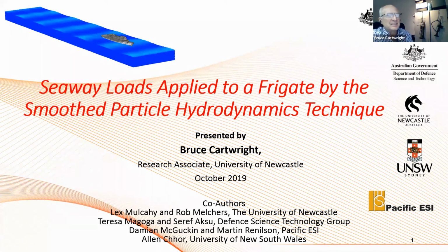It depends what your real interest is in the solution. Is it the bulk flow, or is it detail around edges of these orifices and stuff like that? And I guess it is pretty CPU intensive, so you need to choose the parameters and the size of your model to reveal the data that you want, or the results that you want. So all I can say is, yes, around sharp openings like an orifice, it is quite sensitive to the particle size.